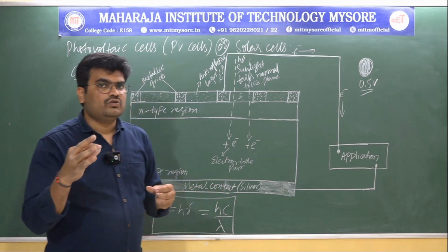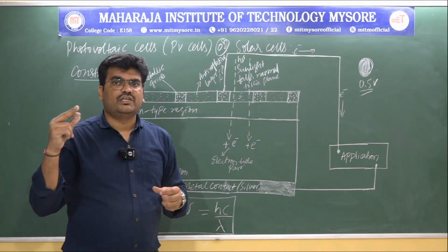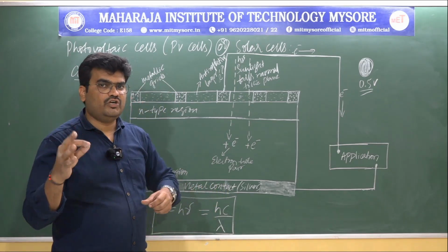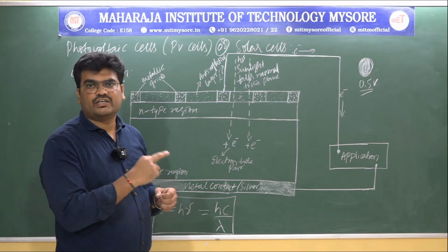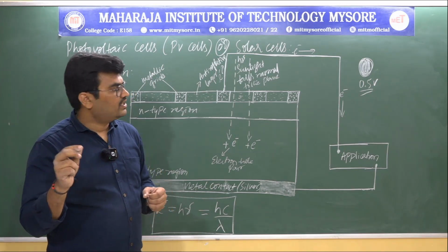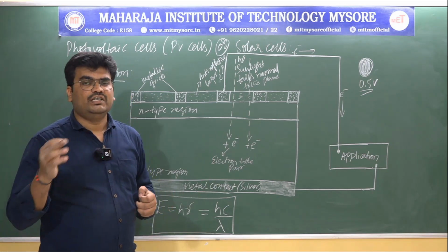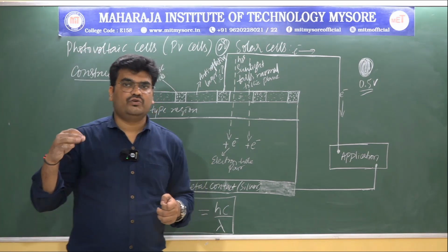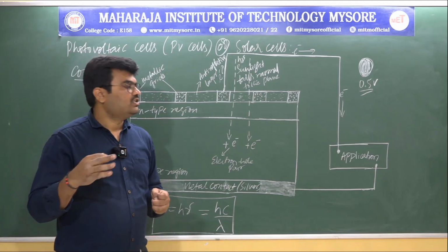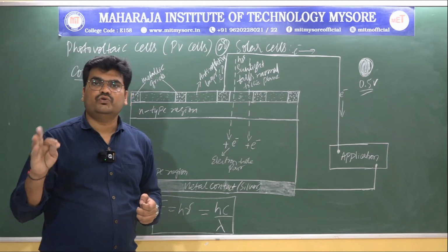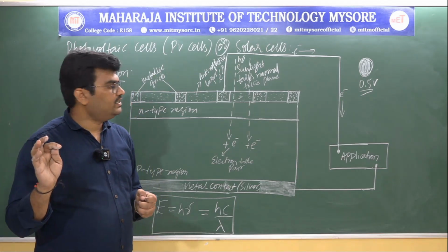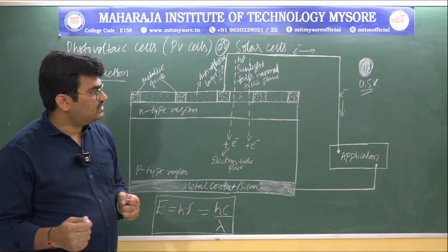That module acts as the basic building block for the generation of electric current using solar radiation. Actually it is supposed to generate 18 volts of electricity, but in reality it generates only around 12 to 14 volts. The remaining electricity is lost as heat, because the cell gets heated in the sun.